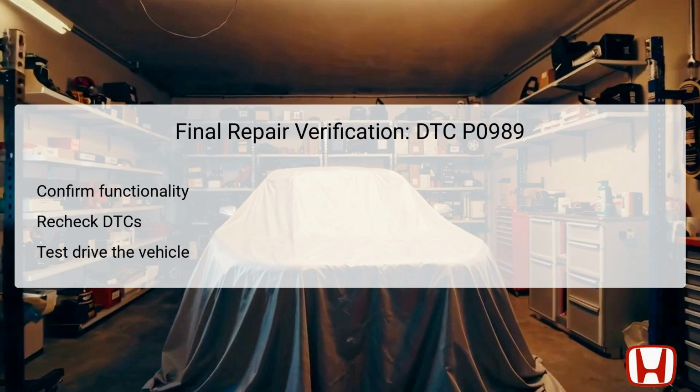Once repairs related to DTC P0989 have been completed, it is crucial to perform a final verification to confirm successful resolution of the issue. Begin by reconnecting all connectors securely, ensuring no loose connections remain. Utilize the HDS to recheck for any stored DTCs. Ideally, there should be no active codes present now. Following this diagnostic check, it is recommended to conduct a test drive under various conditions to evaluate the transmission's performance.